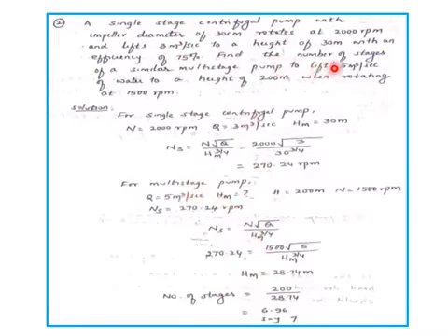Here the data is a little different because we want to lift 5 meter cube per second. Before it was 3 meter cube per second, so the speed was a little more. Since we are delivering 5 meter cube, the speed is reduced, which is 1500 rpm. Here the total head is 200 meters. But we want to find the head produced. It cannot be 30 meters, because we are lifting more water at a lesser speed, so the head has to reduce. Though a similar pump is used, the manometric head produced will be slightly lesser, but the specific speed remains the same.